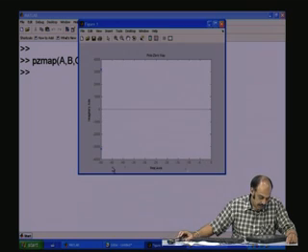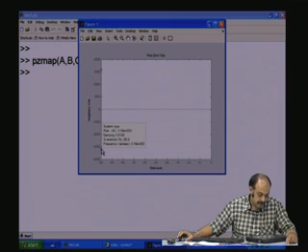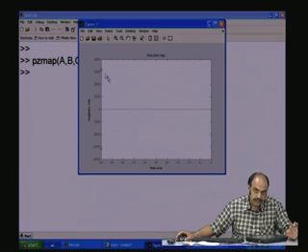You see that at minus 50 you have one pole, two poles. There are two poles, one pole at the positive side of the omega axis, and one pole on the negative side of the omega axis. They are exactly at the same position as far as the projection on the real axis is concerned, and they mirror each other. So, whenever you get a complex pole, you should have another mirror image complex pole on the other side of the real axis.